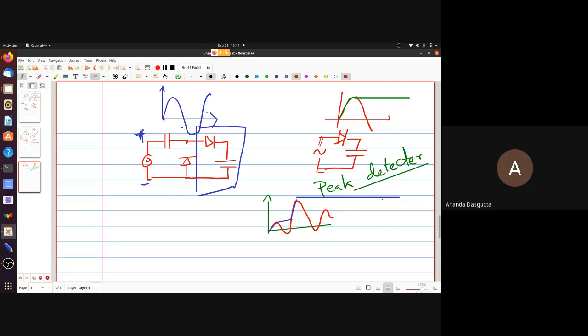So that's what this part of the cycle will go like this. The voltage here. What will happen after that? Throughout the capacitor I have zero voltage, right? Then once the input voltage drops to negative values, the diode will conduct, the capacitor will charge up, and the capacitor voltage will go like this. Initially it will be zero for this cycle, then it will rapidly charge up through the diode, which is now forward biased, until it reaches minus Vp, and after that it will stay there, right?